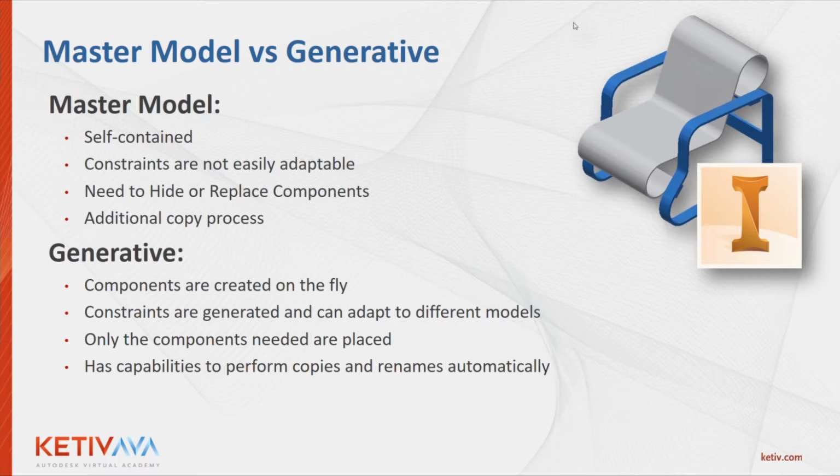So they're going to take this master model, run iLogic on it, and configure it. Then they don't want to modify that original model, so they want to make some production parts, for a particular job, per se. So we can use Design Assistant. A lot of you have Vault, so you're using a Vault copy design process, and that's fine.